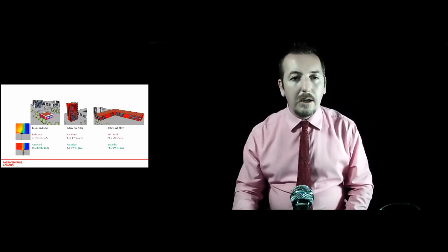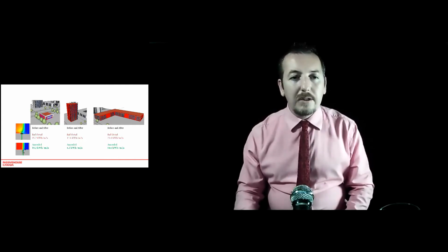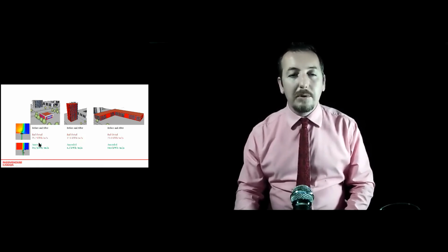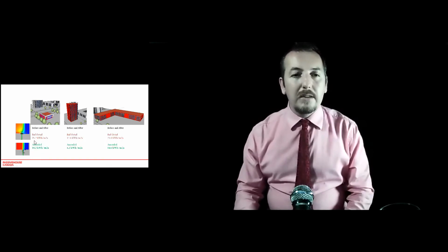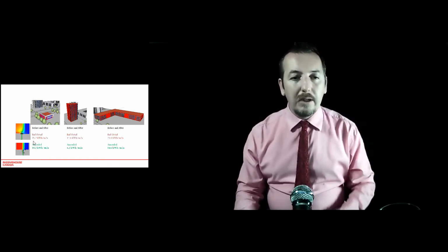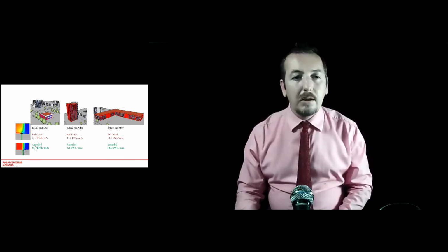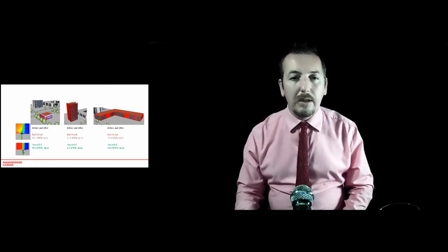Now, here we have, okay, so in one case, the building wasn't actually making the standard anyway, okay? So this should be 15 if it's making the standard, but it's just the way I had the model set up. But with the bad detail, it'd shoot all the way to 25, nearly 10 kilowatt hours more. And with the good detail, it was down to what should be making the standard if we just change the U values.